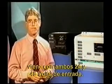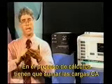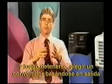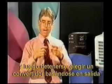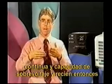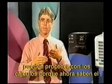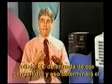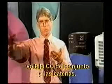So in your process of doing your calculations, that's why you must add up your AC loads, then stop, choose an inverter, and once you've chosen the inverter based on continuous output and surge capability, then you can proceed with your calculations, because now you know the input DC voltage to that inverter. And that's going to determine the DC voltage of your array and your battery.